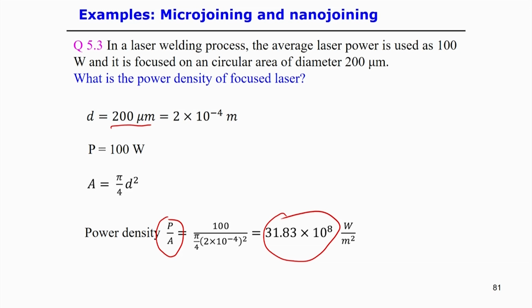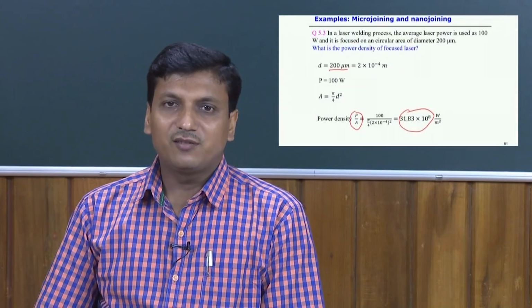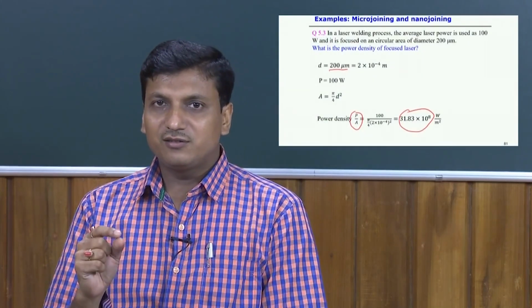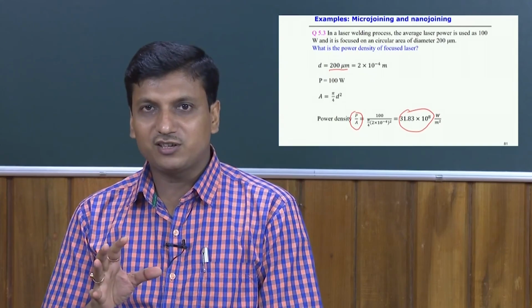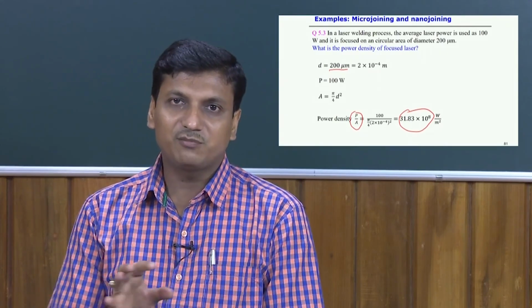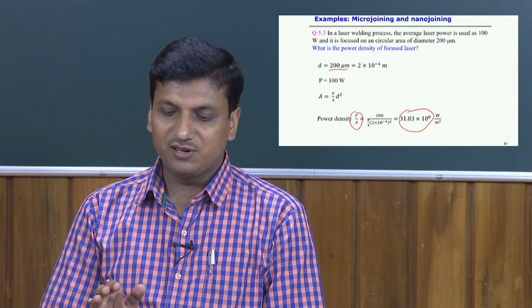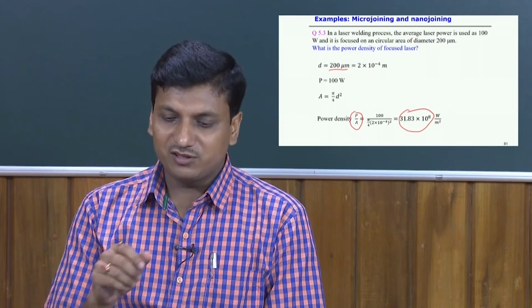We can estimate the power density because sometimes this power density is useful to decide whether the laser focusing on any sample will create a conduction mode, or whether it will create some keyhole formation within the sample itself, based on this power density.